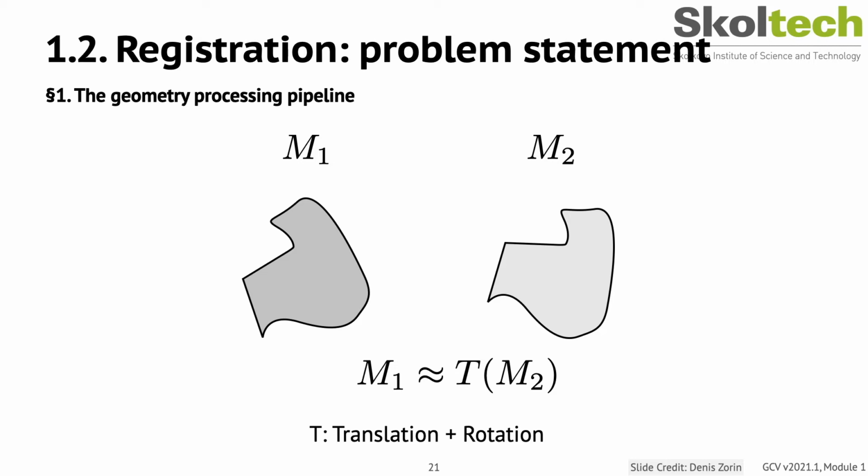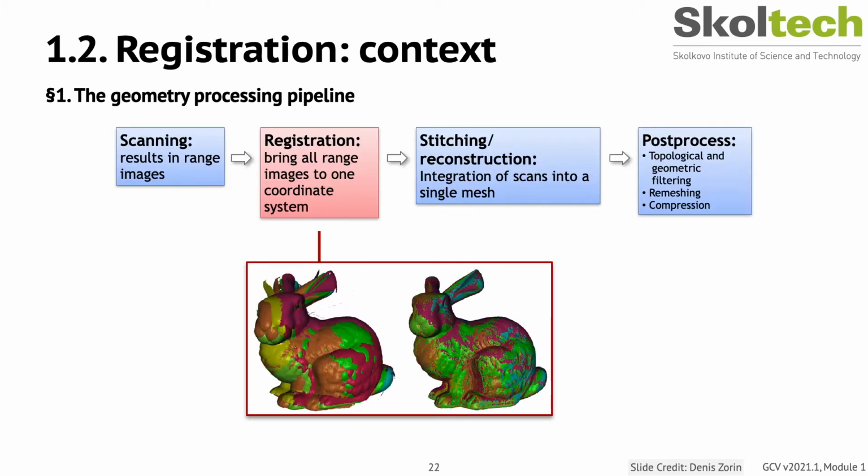This would allow, for example, to determine the equivalence of the shapes by a simple mean square distance metric. For our context, however, we will only use the registration step to align the measurements. So, the registration is based on an assumption that when scanning shapes using high accuracy non-contact measurement devices or by shallow depths of field, uncertainty in different sensed points does not vary by much. So the scans are noisy but not too noisy.